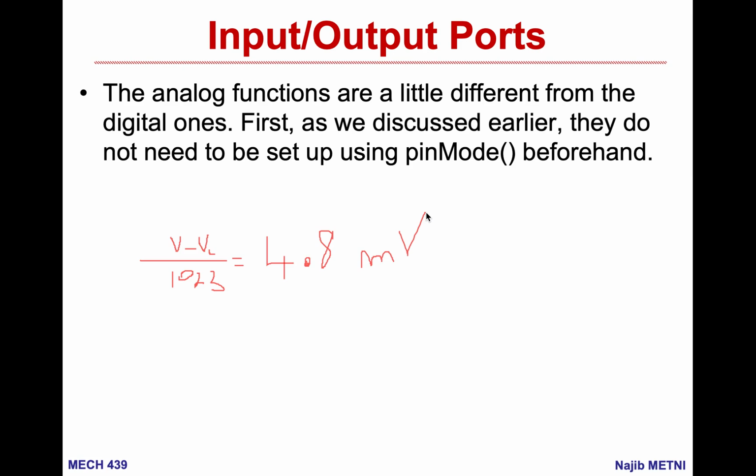For us, maybe it's small, depending on the application. We should see that in some applications this is tremendously high. This is why it's important to amplify my signal before going into the A to D of the Arduino.